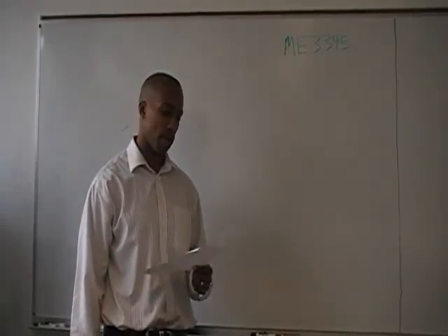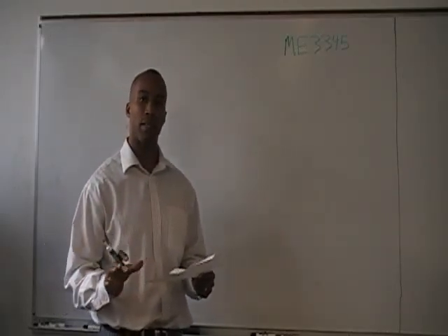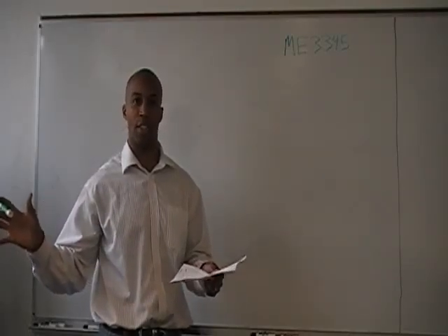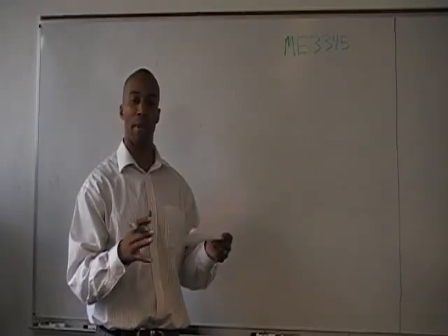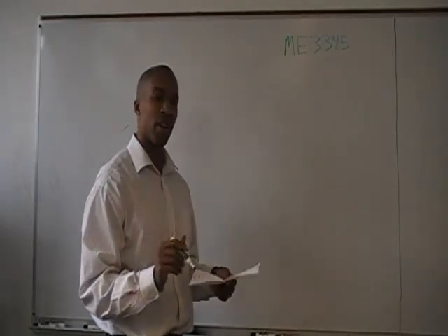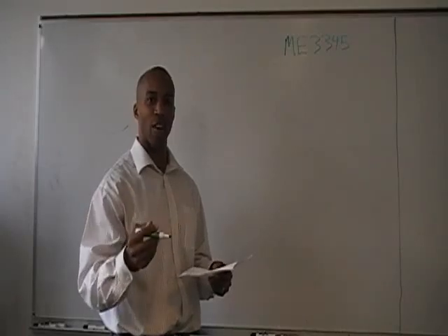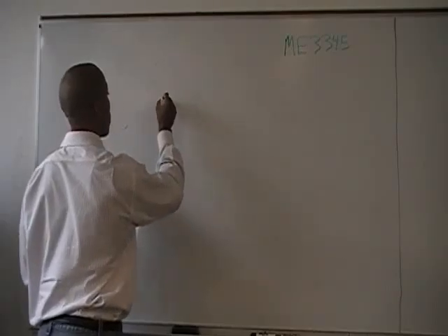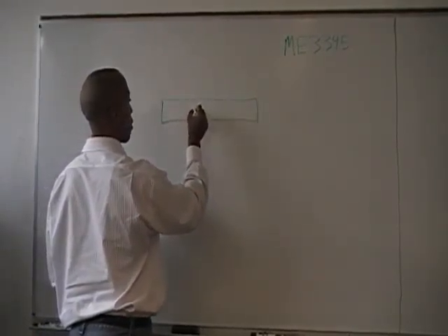All right, today we're going to work problem 1.65, and this problem involves a plate of glass that's at 600 degrees Celsius, and you can imagine it going down a conveyor belt, and it gets exposed to some ambient air at a temperature to cool it down. Right? And we want to figure out what's the air temperature that would keep the temperature gradient in this glass plate from exceeding a certain threshold.